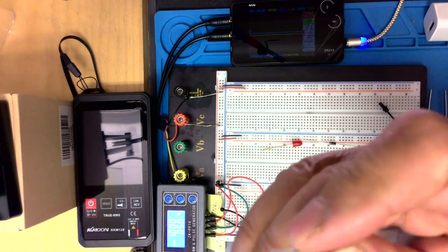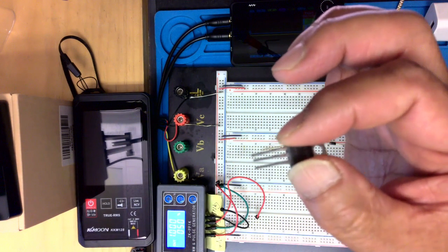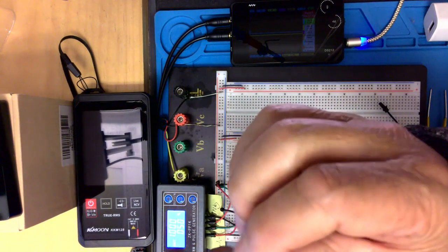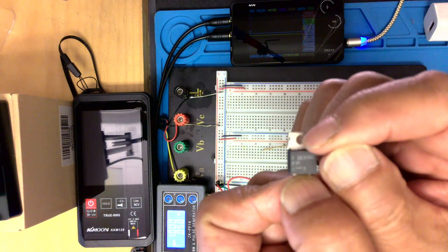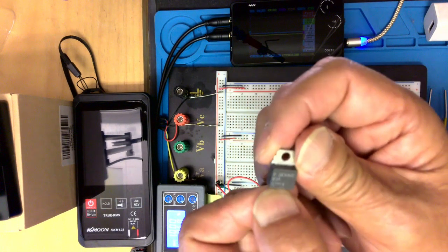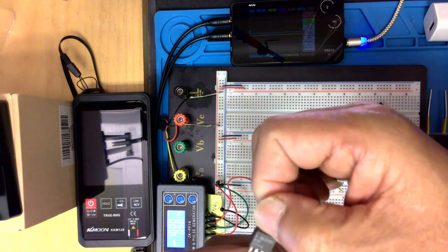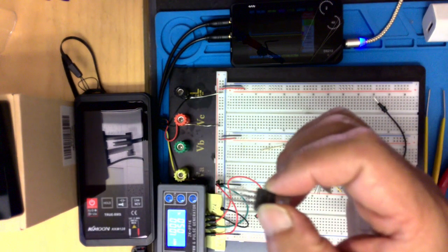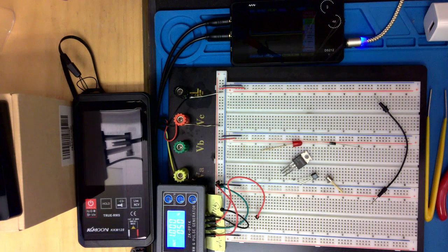So this is a power transistor. For a power transistor, the pin assignment is different because the middle one is the collector, and the metal is directly connected to this heat sink. This is the heat sink. So what you do is you mount it on the PCB and screw it or solder it so that the heat escapes from this. The power transistor needs heat dissipation. Okay, so that's about it.